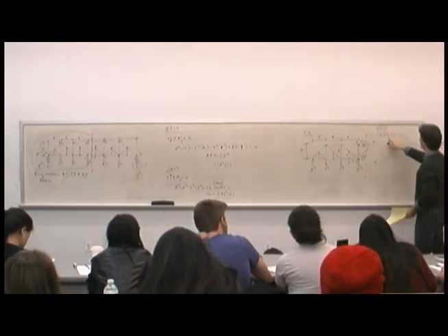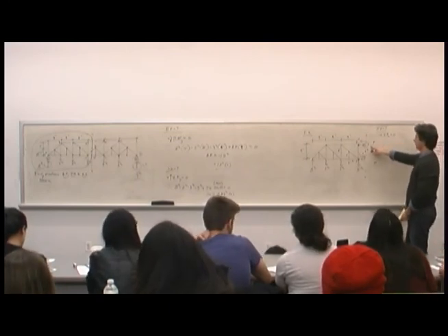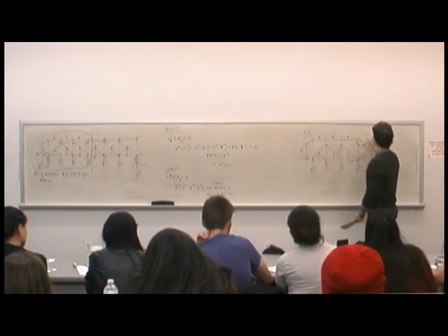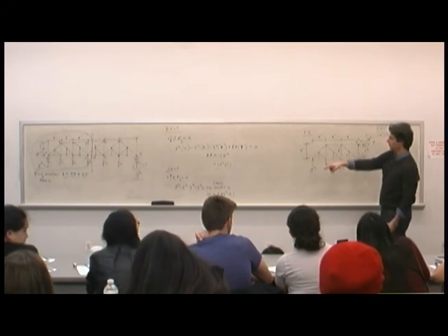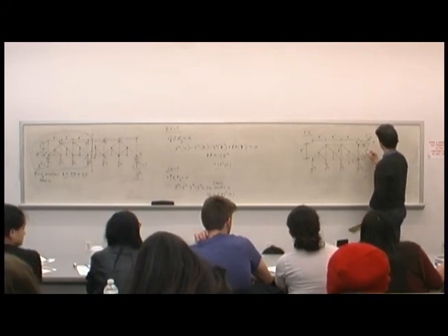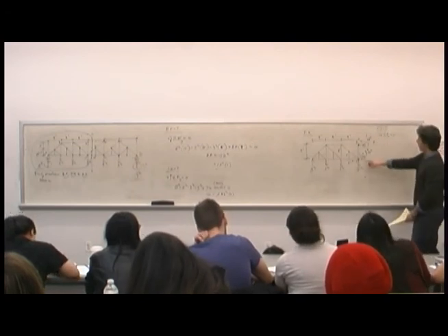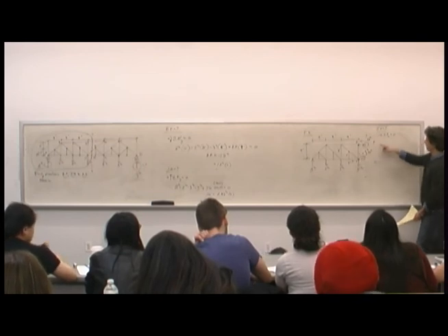Sum of the forces in the x direction give me what? We figured out what EF was, right? What is EF? It's 17 kips. We figured out what JK is. It's 2.83. So I need the component of JK again down here, but let's write the equation.